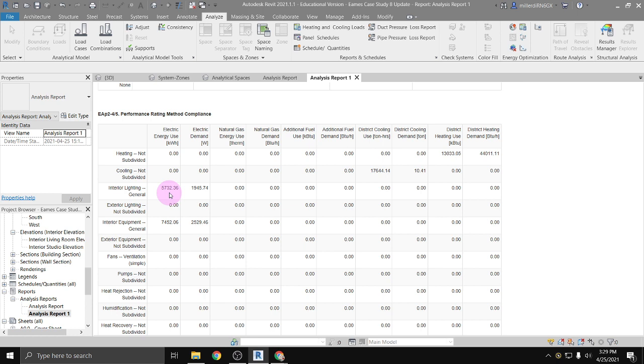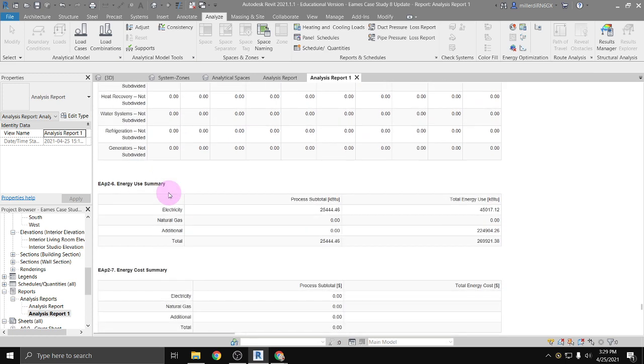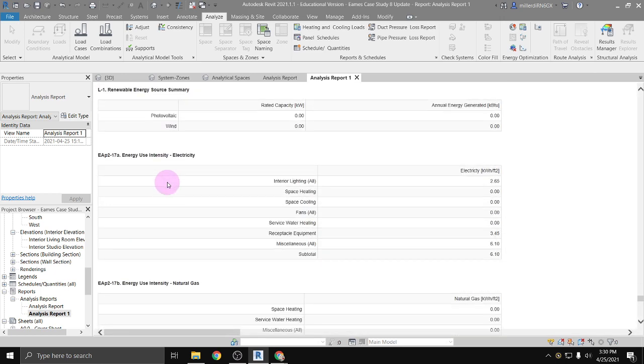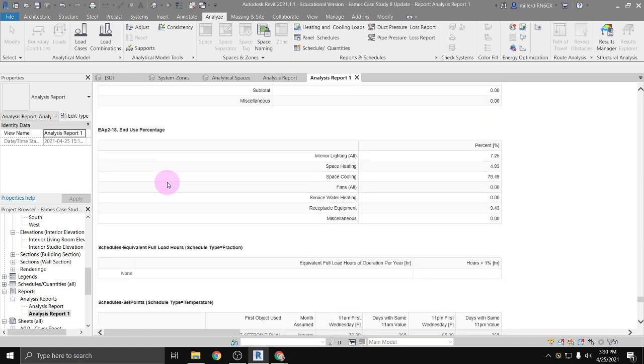You usually know exactly what level of LEED you're aspiring for, and even which areas you are planning on getting your points for. And then when you apply for the LEED certification, you have to provide all of these justifications for why you got those points associated with daylighting. You can then use these reports to say, well, we're saving X amount of electricity because we can see from the solar analysis that we're getting plenty of natural light exposed from the south and things like that. So these reports can be very helpful.